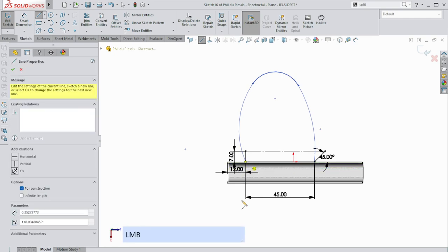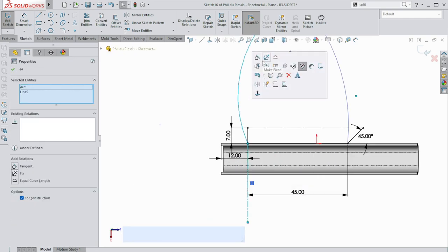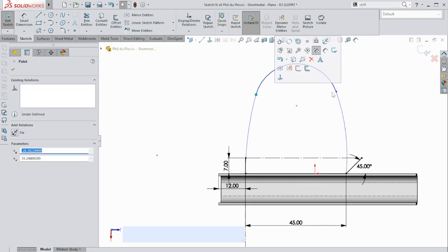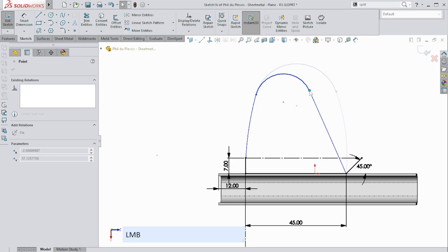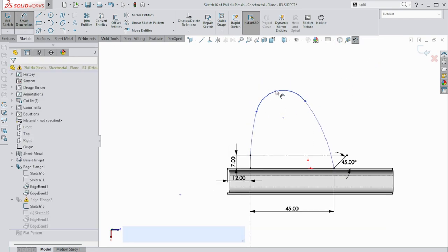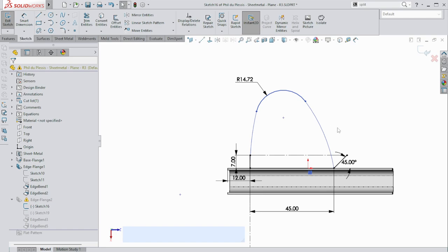Right, so if I just put in a vertical there, construction line, and I got those to be tangent, then I can start fiddling with this to get it to kind of do that kind of shape. Right, then obviously with some dimensions in, they will give you more control, and then with the height, say that center, even more. All right, so that would be the simplest way. Then you don't have to have these lines. But let's do the slightly more complicated way as the example.